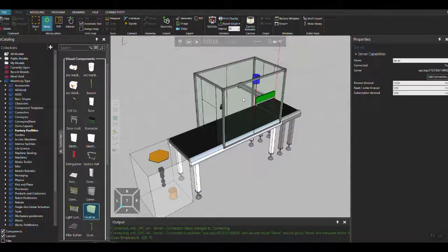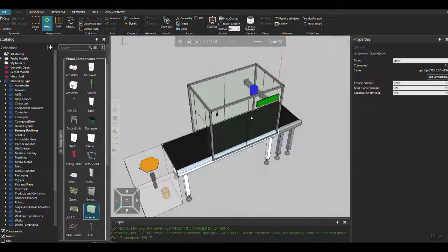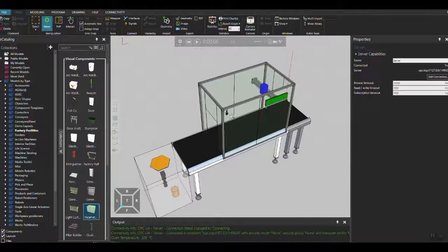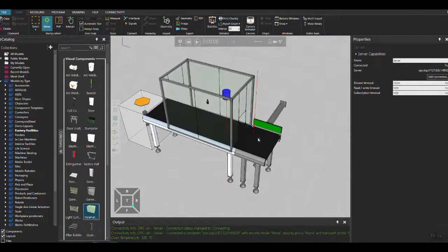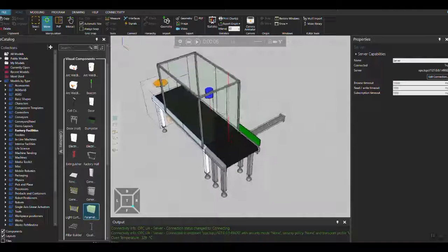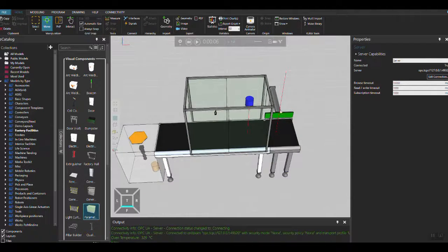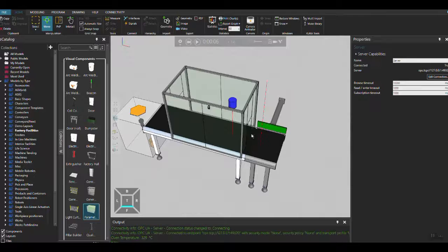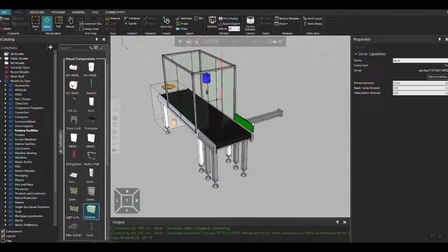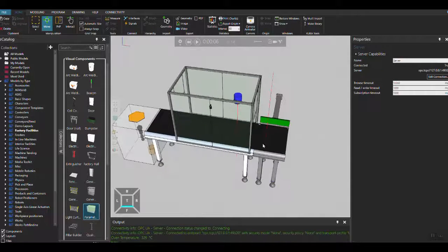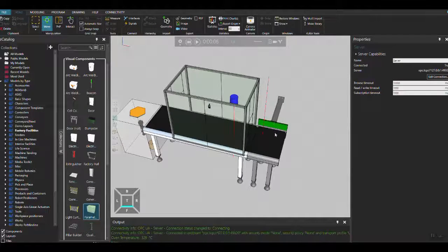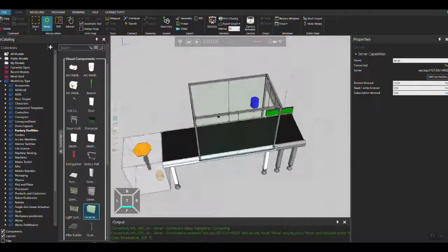There is this oven, and this oven is kept at a temperature which should be between 320 and 350. After the parts go through this, there is a distance sensor. It measures, and if the distance is satisfactory, then it goes through. Otherwise, this sensor throws a signal, and after calculation, the PLC gives a signal to this pusher cylinder, and then that part which does not have the satisfactory height, this piston pushes it out of the conveyor.